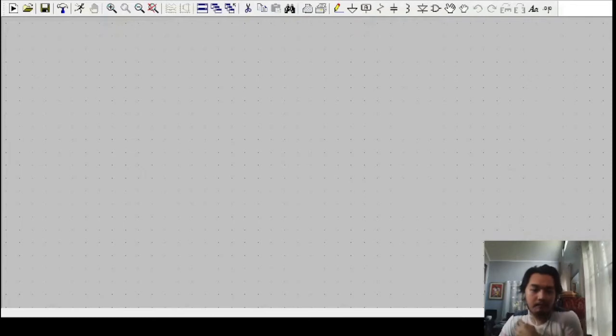So the first step for the procedure is to generate a BPSK signal. We need to create the BPSK modulator circuit, which was given, to generate a BPSK signal using LTSpice. So I will now be creating the circuit in LTSpice.